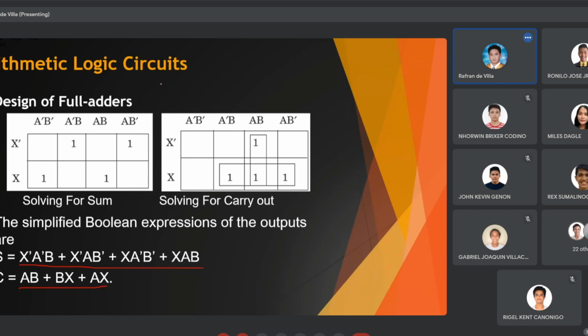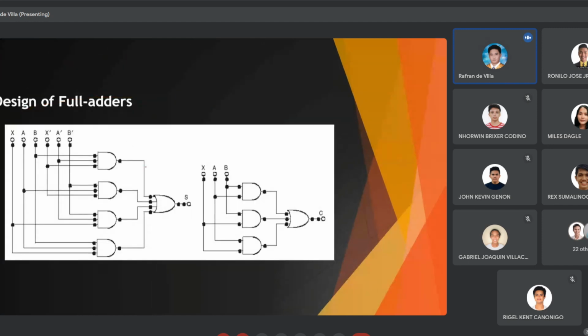So, essentially, if we are to construct the circuit for this one, this will be the design. Okay? So we need a 3 input AND gate and a 4 input OR gate. Okay? So let's say for example, if this is going to be implemented using two input gates only, using the idea of, did we already discuss fan in and fan out, guys?